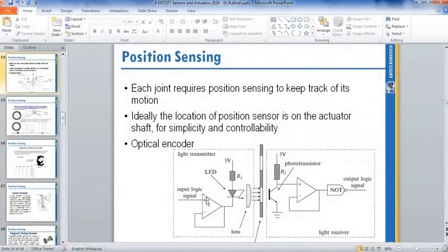So you give a signal here. Sorry, this is 5 volt. Go through R1. So what is the function of R1? R1 is to reduce the current. Because at 5 volt, the current is high. So you need a load to prevent the LED from burning.